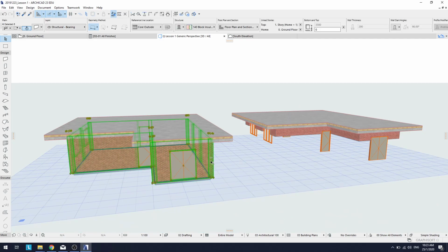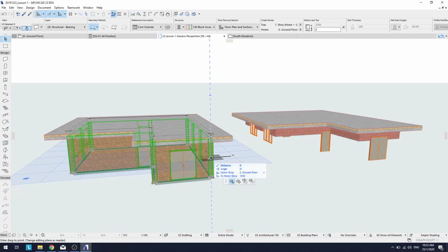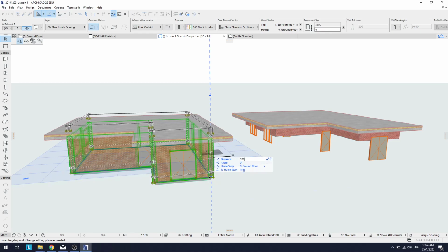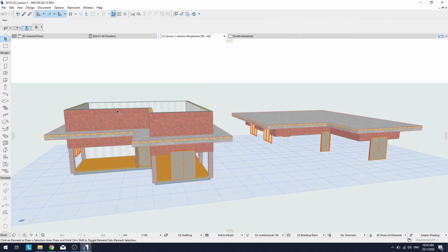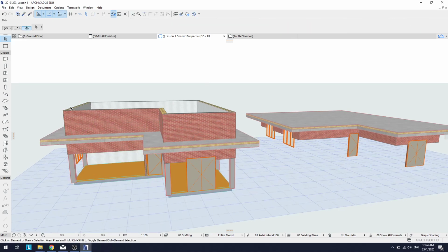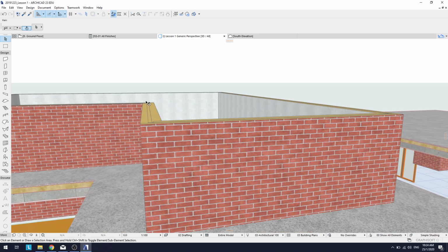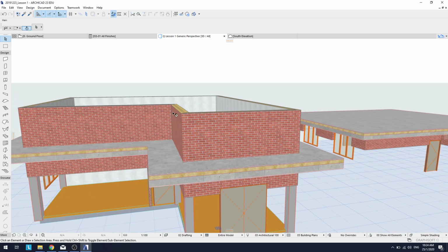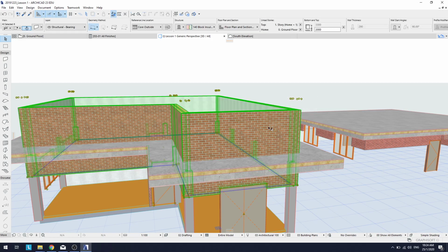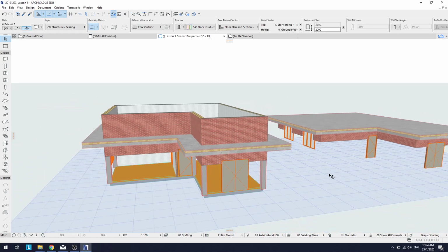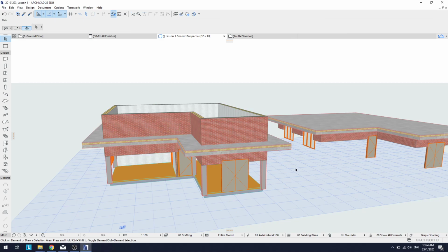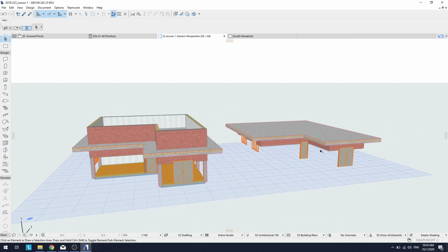But remember for this one we are using crop, and if I move it, it does not affect the geometry at all, because the geometry itself has actually been cut by the roof. So you see here, and that is actually the difference between the associative operation, which is the trim tool, and the non-associative operation, which is using crop to a single plane roof.